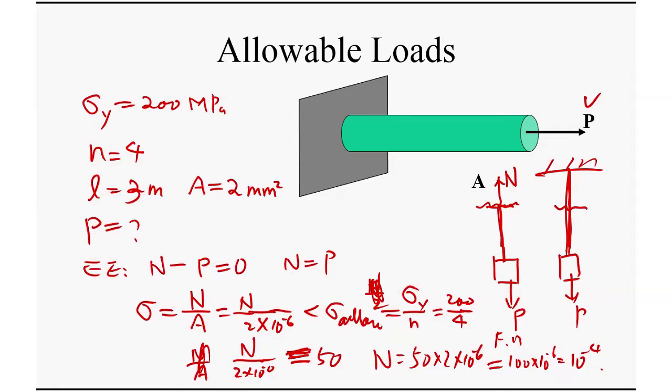Why is it so little? Something is wrong. I know something is wrong, but can you find what's wrong? The unit. Yes, megapascal. You mixed something up. This is a megapascal, so here it is 10 to the what? 6. Remember here you have 10 to the minus 6, but here it is 10 to the 6. So these two actually cancel out. So what should the answer be?